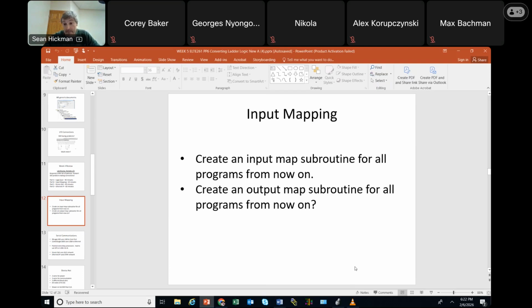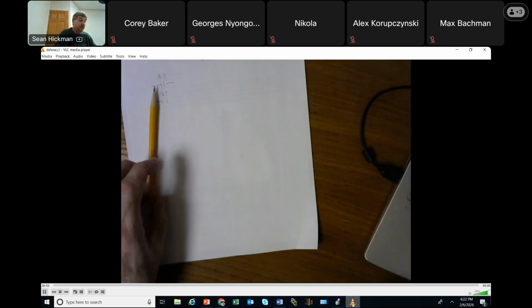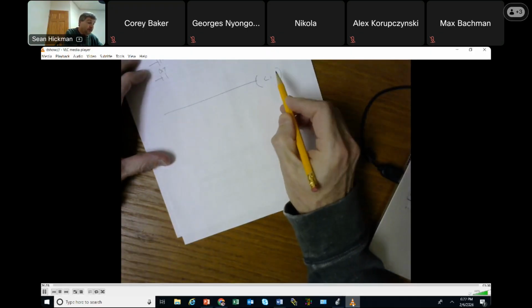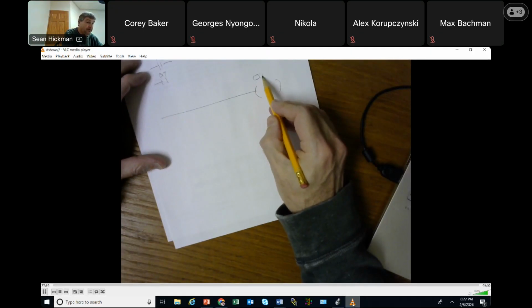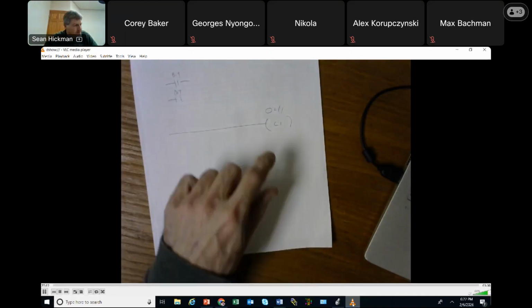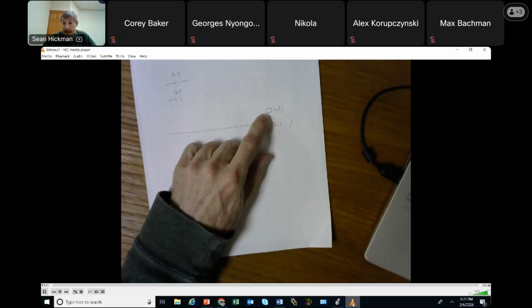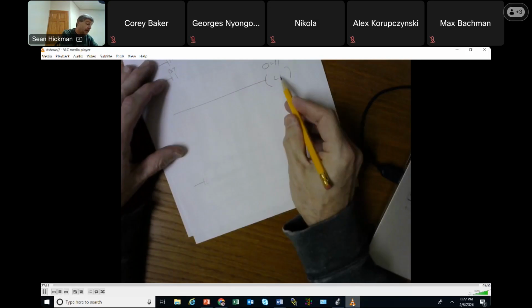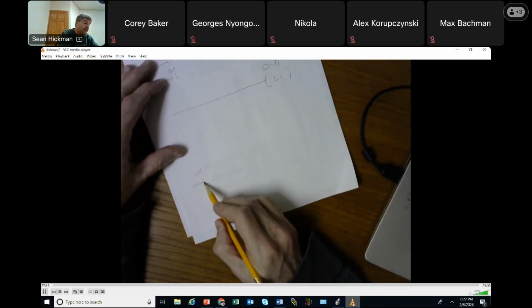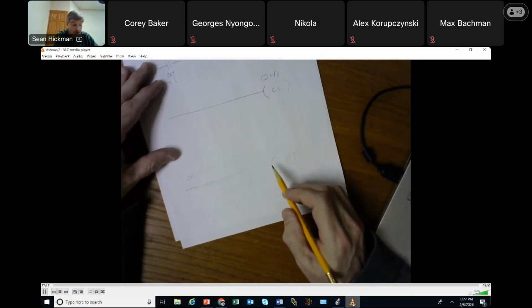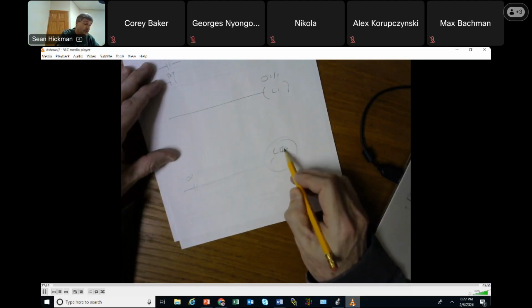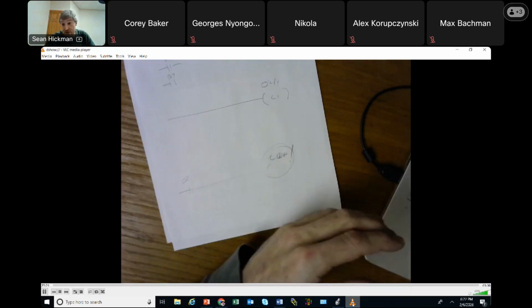If I map the output, all right. So let's say I had something here and I had light 1 and this was output 2/1. If for some reason I did map this light into a bit, then you're going to have a sub somewhere that's going to have this. Output 2/1 is really just going to be a bit called light, so now all of a sudden, light 1 is fictional again.